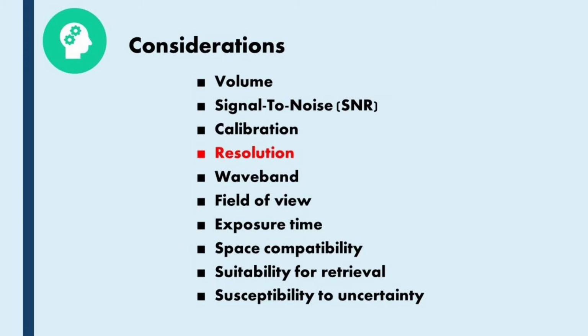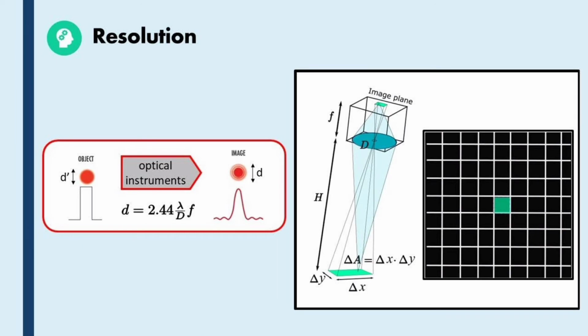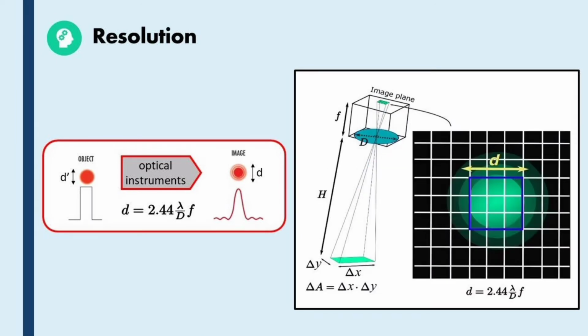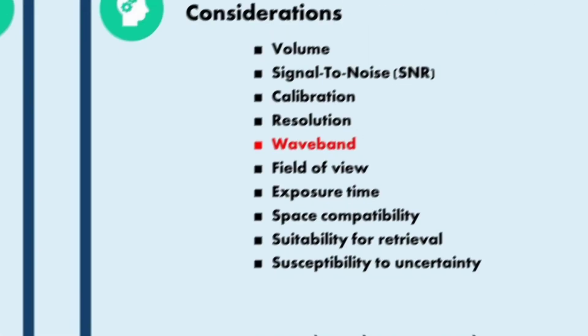This affects also resolution considerations. We require high spatial resolution for analysis of small clouds. The preferred ground sampling distance, or GSD, is 20 meters at nadir. However, diffraction effects limit the resolution. Narrowing the point spread function at long wavelengths requires larger optics, which challenges our volume constraint. So for our SWIR payload, we had to settle for a GSD of 50 meters.